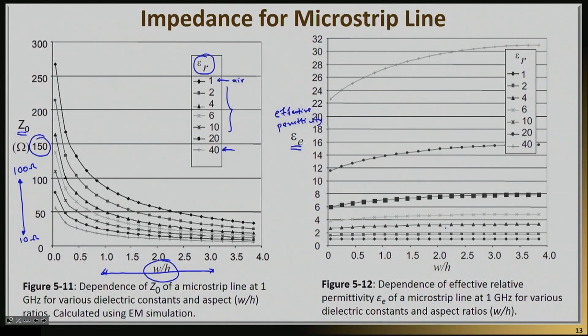but if you go to industry and you ask somebody, can you please design me an impedance of 1 ohm or 500 ohms, you're risking losing your job, right? So that's not possible. Most of the time your impedance will actually be in that range. And that's true not just for microstrip line, it's true for most transmission lines. We'll discuss in a little bit, next slide actually, what happens if you really try to push that and where you're going to get severely penalized. But for right now, let's keep that in mind.